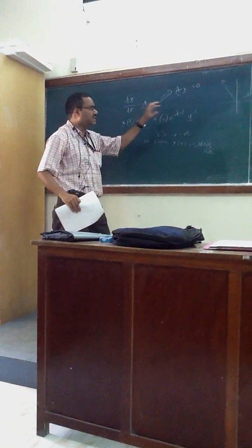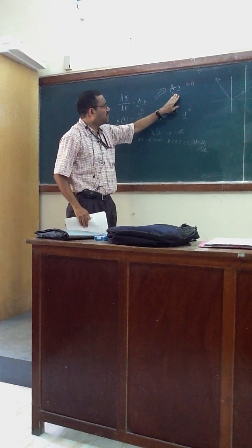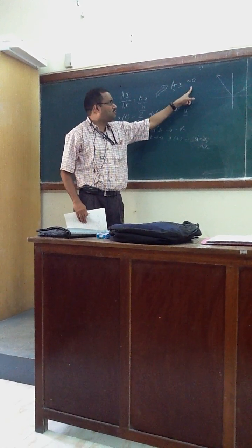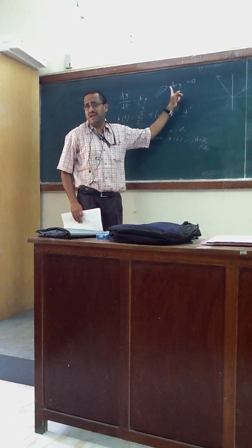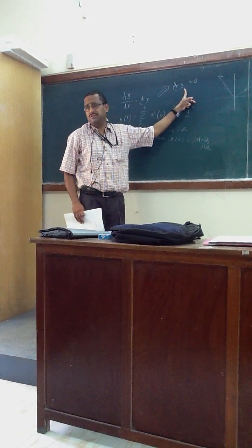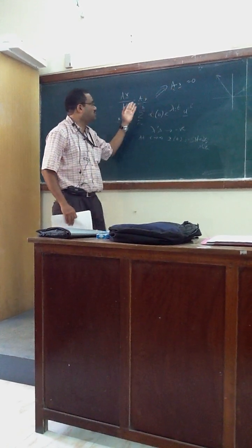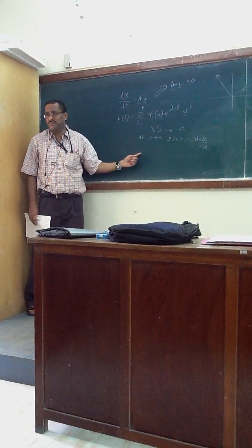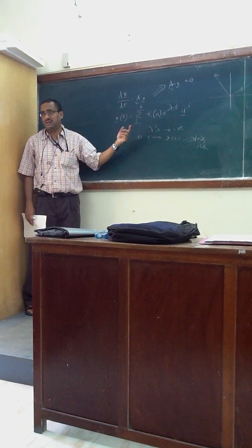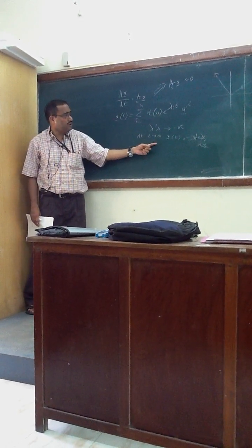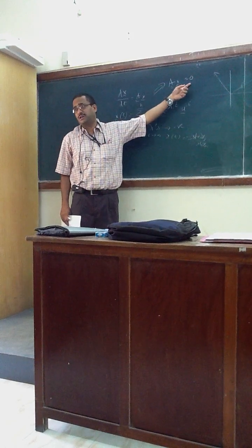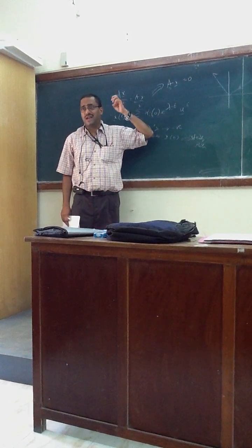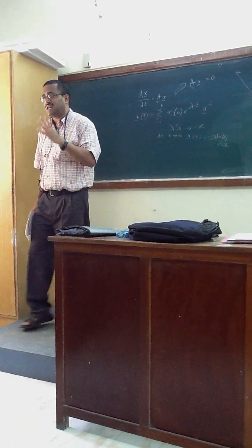So in that case, what actually happens? Even if you get a non-trivial solution, you will not get a unique solution here, because Ax equals 0 belongs to the null space. If the determinant of A is non-zero, x should be trivial. So in that case, the solution at steady state requires the initial condition, and you have to do time marching. We have done the unsteady state solution last class. You put t to infinity, you got the steady state. You could not get it from Ax equals 0 because you won't get a unique solution. A unique solution can be obtained if the right-hand side is non-homogeneous.